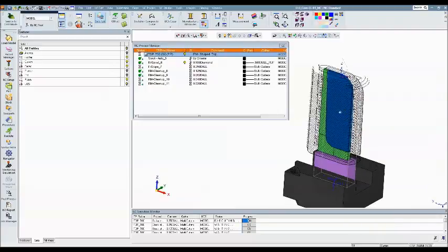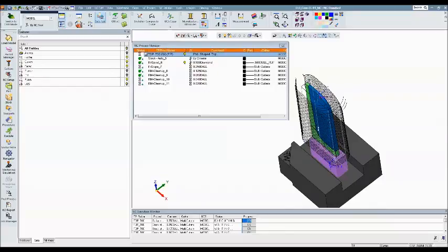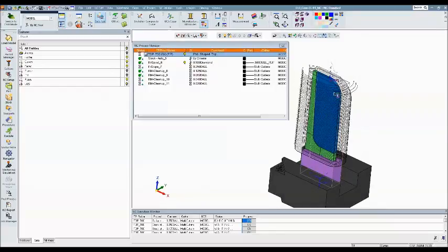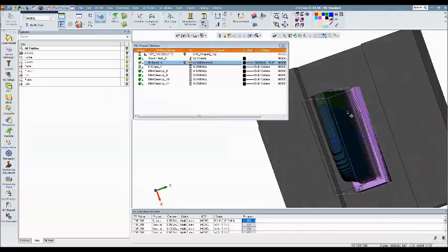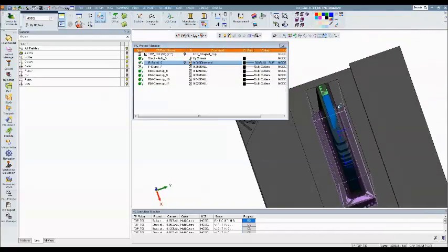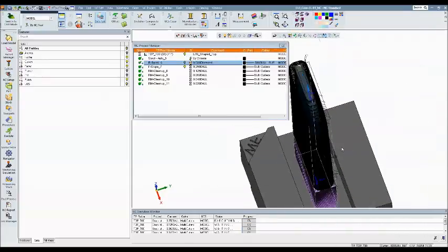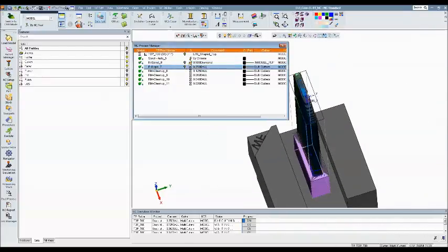And this is a tall electrode, and it's fairly thin, so it has to be processed in a certain way. We want to actually do like a top-down approach, keeping the strength of the electrode while it's being machined. And so after the first rougher is done, it's going to leave it kind of thick like this, and that way when the finisher comes in, it's got rigidity as it's being cut.